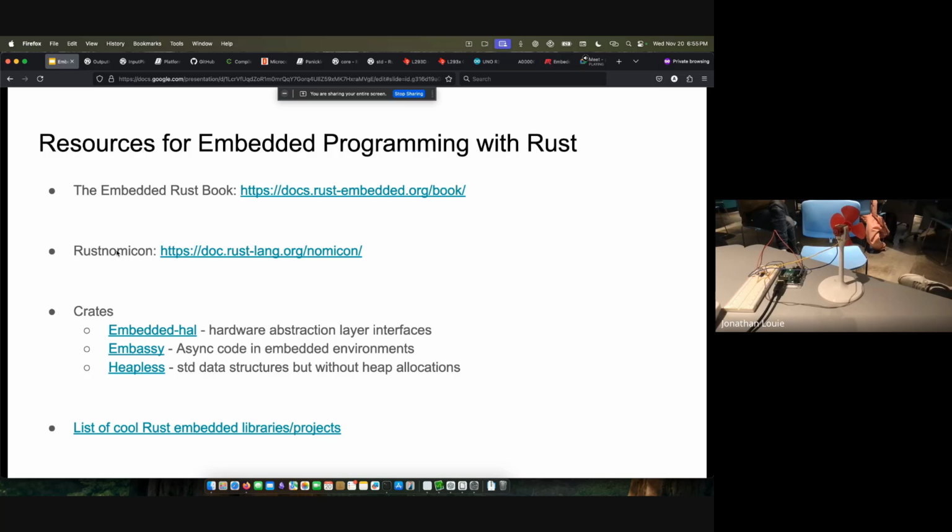Other than just working with your peripherals, whether it's the I2C two-wire protocol, or the SPI, or the pins themselves, the abstraction layers are designed in such a way that pretty much all your stuff gets to remain safe Rust, which again is a huge improvement over something like C, where you could easily mess something up, and debugging in this case is much harder. So that is actually a very nice feature of the hardware abstraction layers.